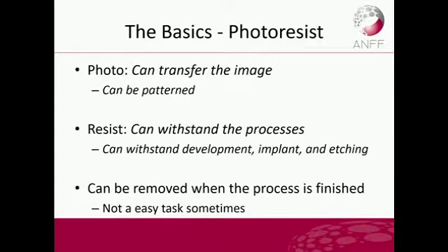And resist means that for this polymer, not only do you need to be able to take a photo, but you also need to be able to resist something, such as the development liquid, and you need to be able to resist the implantation of your ions or etching and development. So photoresists are really important because you need to have certain stability in order to carry out all these processes sequentially.